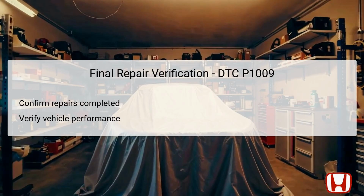This includes confirming the replacement or cleaning of components, like the VTC strainer, solenoid valve, and actuator, as well as ensuring that all oil passages are free of debris. Following this confirmation, it's important to verify the vehicle's performance on the road. Observing how the vehicle behaves under different driving conditions will help determine if the issue has been adequately resolved. Ideally, the vehicle should exhibit smooth acceleration and consistent engine performance. Documenting this verification step is vital for future reference and customer satisfaction.